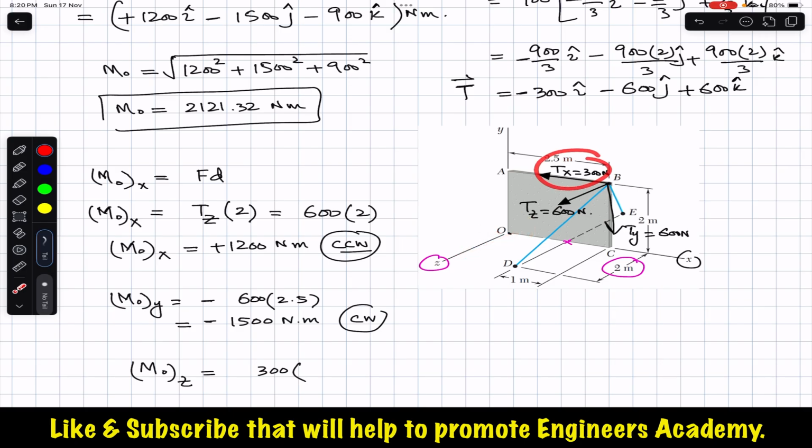So this means that this Tx is producing the counterclockwise moment about the z-axis. So we have to write plus sign here. So plus 300, and the perpendicular distance of this Tx from the z-axis is this distance. This is the perpendicular distance, which is 2 meters. So 300 into 2. This is the moment produced by the x component about the z-axis at point O.